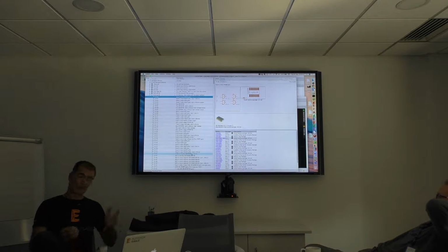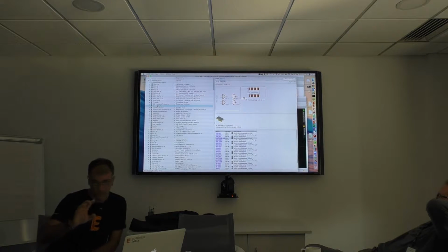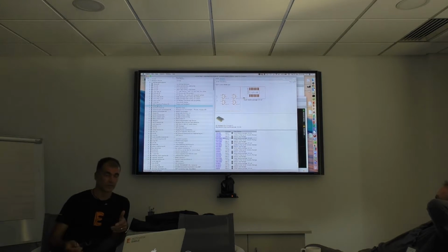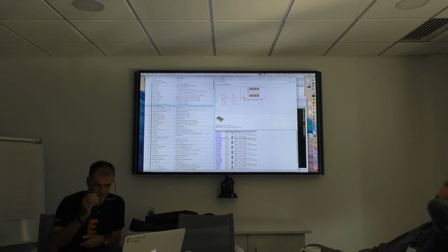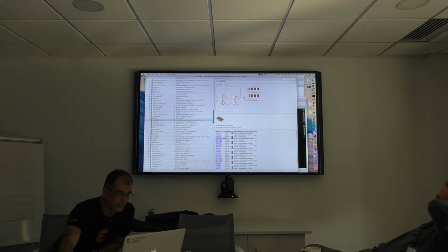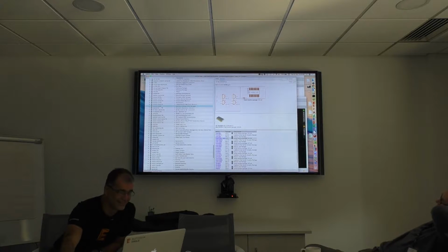So we also have components, sure, later. What you need to know is there are a few libraries you should know. There's one called RCL, with resistors, capacitors, inductors, something you always need in a design. We have linear libraries, we have linear stuff. We have diodes, we have transistors, so there are different transistor libraries. That's also something you want to clean up because there are too many transistor libraries. We also have too many resistor libraries.